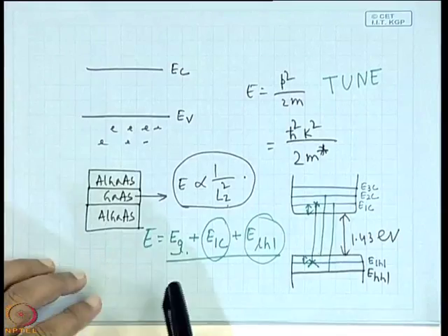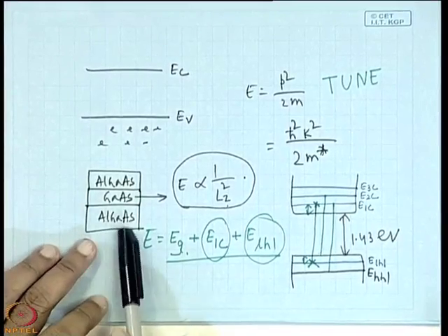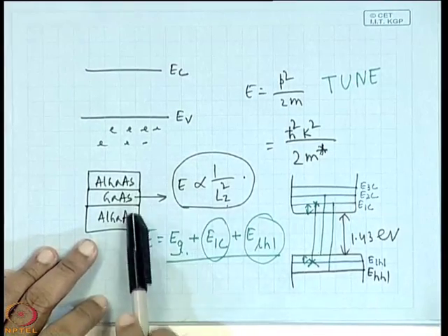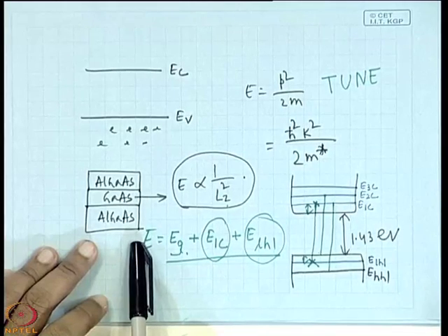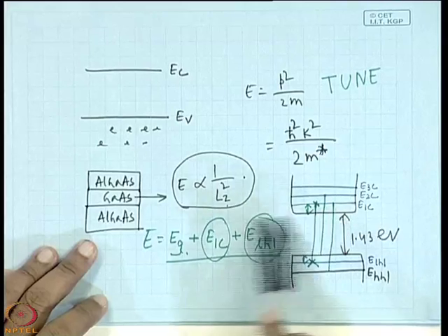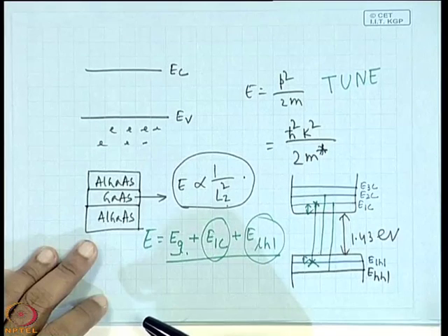And in quantum dot the advantage is that depending on the dot size, the energy is split. I have given you the splitting of the energy levels here. In this diagram it is quantum well basically that I have drawn, but in quantum dot also the splitting will be there, and it will be inversely proportional to the square of the diameter.